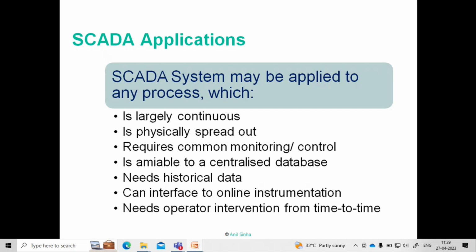Number one, it may not be economical for me to do so. That power station, what fuel am I going to use for it? Fuel has to come from somewhere. Then the size of the power plant which I set up will not be as big, or therefore as efficient, as a super thermal station which I can set up in, say, Jharkhand, where coal is available just next door. So they can afford to build huge power stations which can produce power at a very cheap rate. And then it's only a question of whether we can transmit it. How can we transmit it?